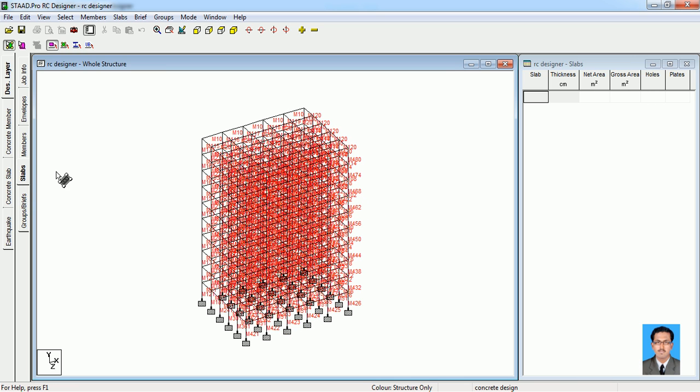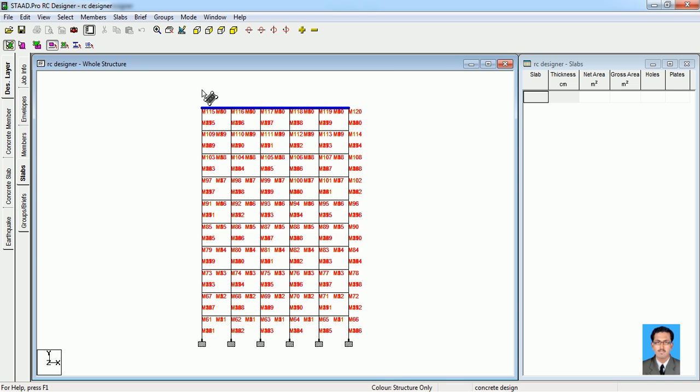Then I'm going for slabs. We have already created some slabs. In the same case, if you check, all the top ones will be created as a single slab. So I can drag and select, and then I'm going to go for slabs and then Form Slab. Like that you can repeat the process.